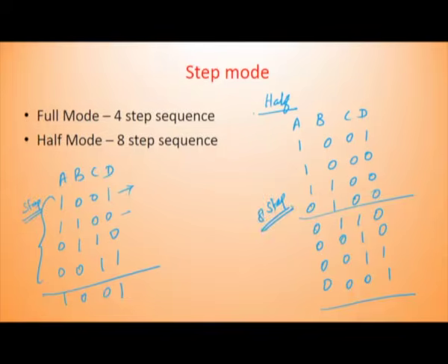Now, I start to write the program. How we start to write the program means we have to load the initial value first. Okay. Suppose if you want to activate this, I want to set this bit position, then clear, clear, set. So, how I have made the connection. Based on that, suppose I connected port 2.0, port 2.1, port 2.2 and port 2.3.